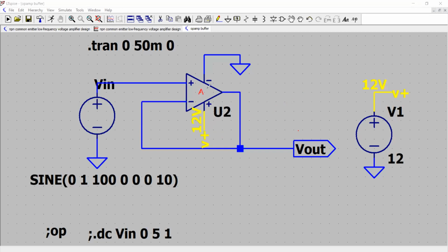So I have a positive input. The operational amplifier has a gain A, which is called the open loop gain. Open loop gain is very fondly called AOL, and usually it is in the range of 10 to the power 6 to 10 to the power 7. For a special op-amp, it could be in this range. So how do I ensure this has a gain value falling in this range?